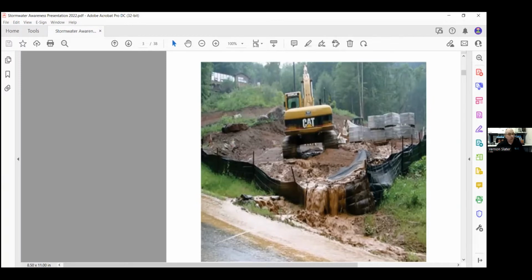Excessive turbidity or suspended solids absorb more energy, raising the water temperatures. And the prediction is by the year 2200, the current models show all ocean ecosystems will have been changed by temperature increases, and many fish populations will not survive unless we do something now. Large amounts of suspended solids or clays may clog the gills of fish and kill them directly. Excess turbidity may bury and kill eggs laid in the bottom of lakes and streams. High turbidity blocks out light penetration that other beneficial plants and organisms need to grow.